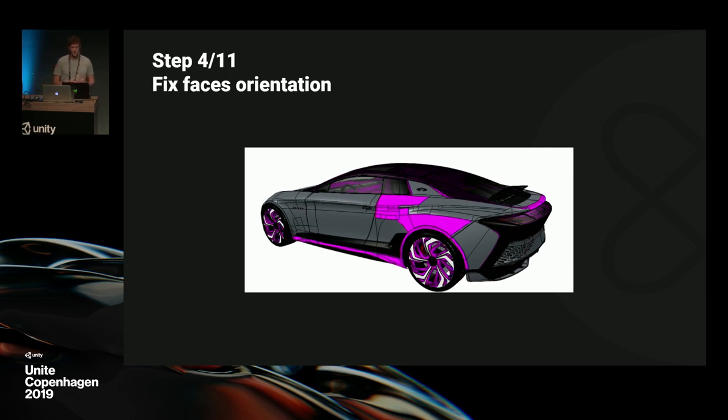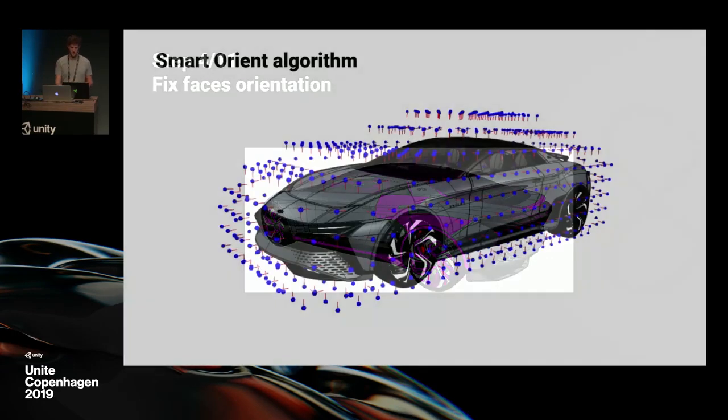And as Cédric said, the repair mesh function sets orientation per propagation, but some incoherencies remain here. It's due to the fact that we have only surfacing patches, which are very, very hard to orient. So for these cases and for these surfaces we see here, what defines which face orientation is correct will mainly depend on the user's point of view. So here we'll use another algorithm we call Smart Orient. And this function will properly orient all polygons in the same direction automatically, according to external points of view.